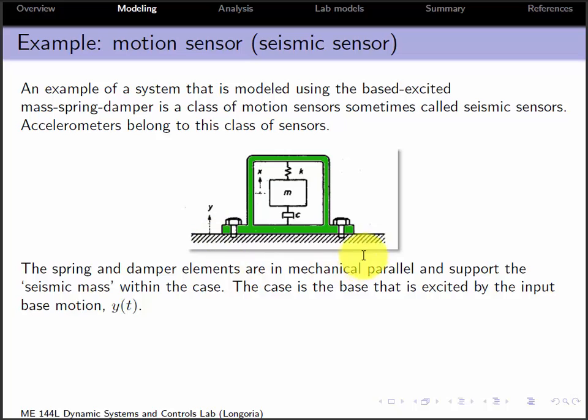And so this is a seismic sensor, and depending on how it's designed, it could be used to measure vibration, obviously, but actually it could be used to measure either velocity or acceleration or displacement. So look in the reference that I've put on the course log by Thompson. He may have some discussion on that there.